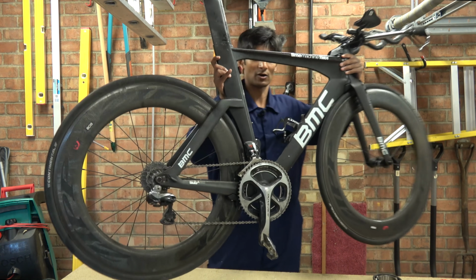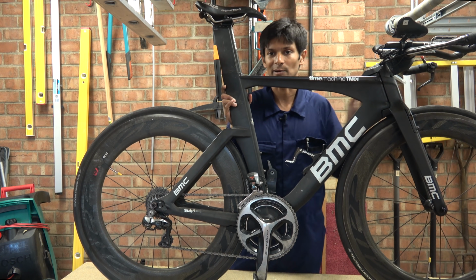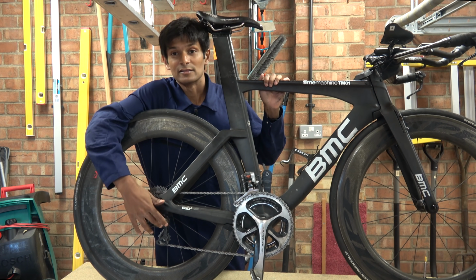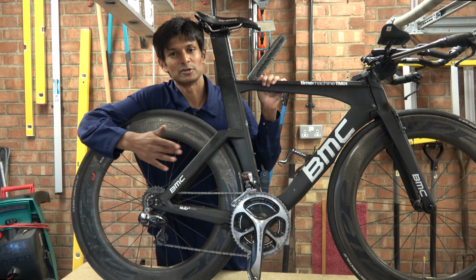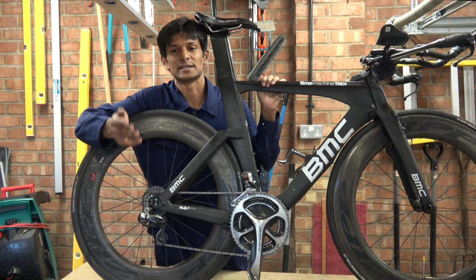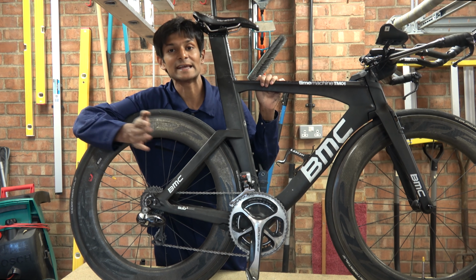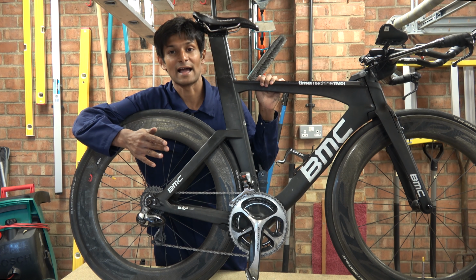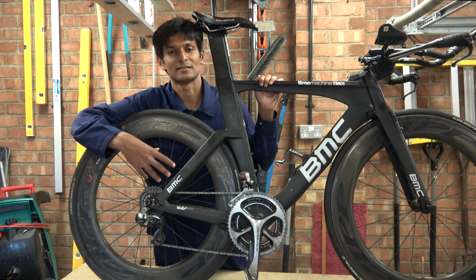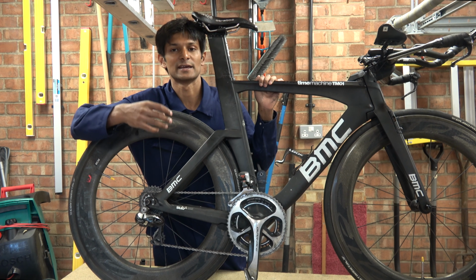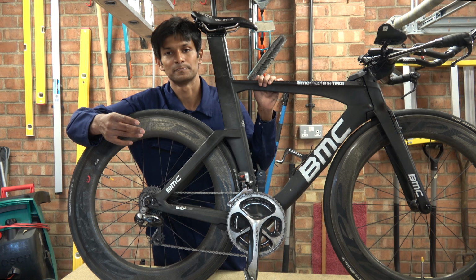Then as we go towards the rest of the bike, the back of the bike, the pulley wheels, they are predominantly radial load. There's not really much axial load until you change gear. At the point where you're changing gear, there's a lot of axial load. Once it's engaged and the chain has moved to the next set of teeth, the axial load is diminished and you are still in radial mode.